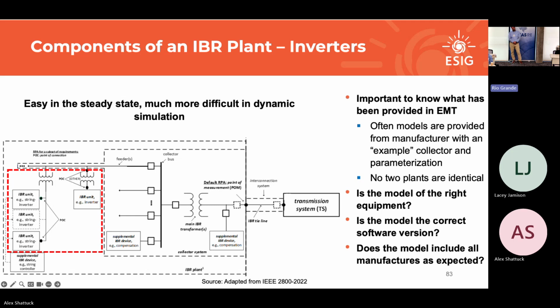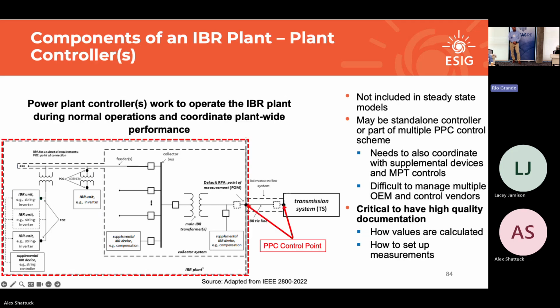If you know this is a complex plant with two different manufacturers of the inverters and a supplementary controller, and it's just one inverter manufacturer model and one inverter manufacturer PPC, that's another red flag to dig into. So while it seems like a simple thing in the EMT, I got a model from the manufacturer, I'm running it, or I got a model, I'm cutting and pasting it, there are a lot of other considerations to make sure that you're not starting from a completely wrong starting point.